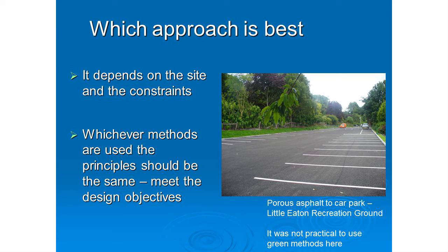I think Alistair said this, Bridget said this. And a lot of sites we work on, there isn't a lot of open space. So we end up putting a lot of engineered systems in. But our starting point is always to look at what open space is available, put what SuDS we can in there. And that does depend on clients, if they want open water or not. And then work backwards from that.